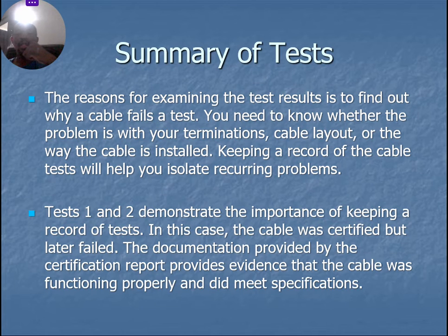So you need to know, is it the termination point? Was the cable not terminated properly in the modular plug? Was it not terminated properly in the modular jack? Was it not terminated properly in the patch panel? You have to find out. Or was it the laying out of the cable that was the problem? It was not laid out properly. Or the problem was that the cable itself was not properly installed. Or could it be the manufacturer's problem? Okay, so all of this we have to take a dynamic look at and differentially come up with an absolute conclusion from this test result.